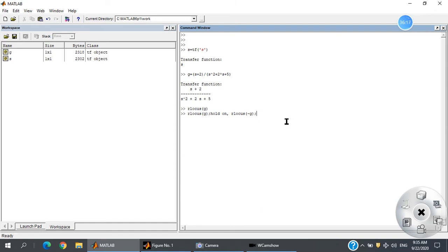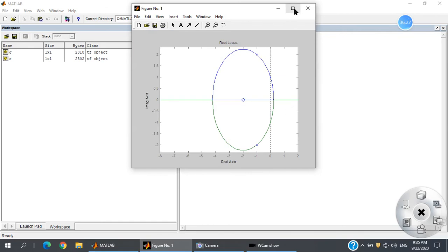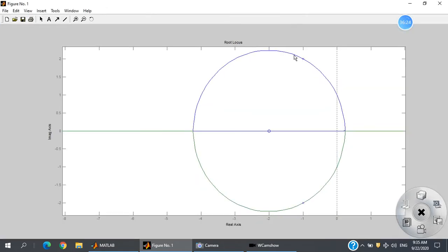Okay. Oh, there's a blue circle. Now see the mouse. I move in this direction and click. Yeah, this side is for positive K. So this is the departure direction, right? And this place will be negative K, so this is arriving to the pole.